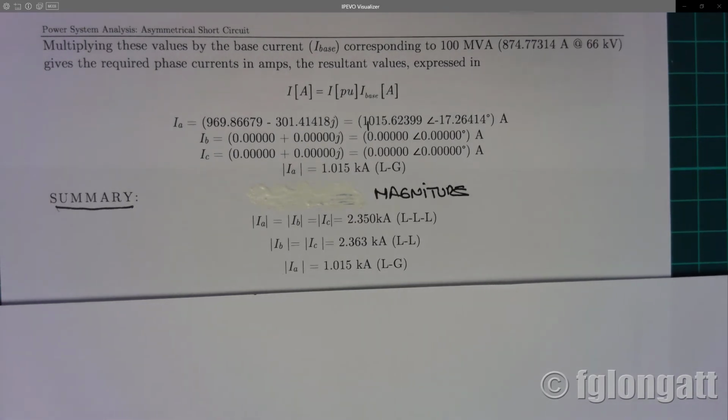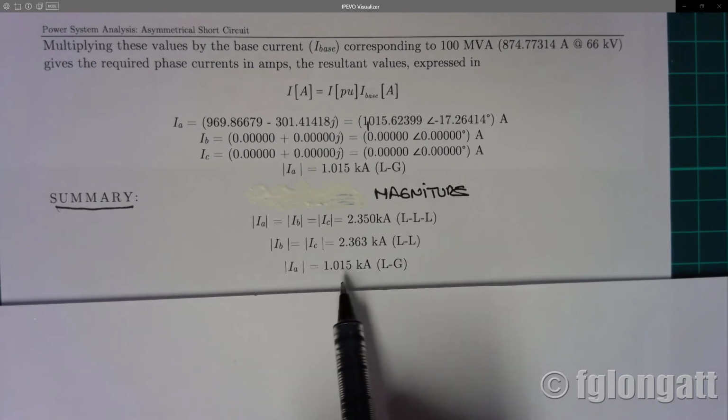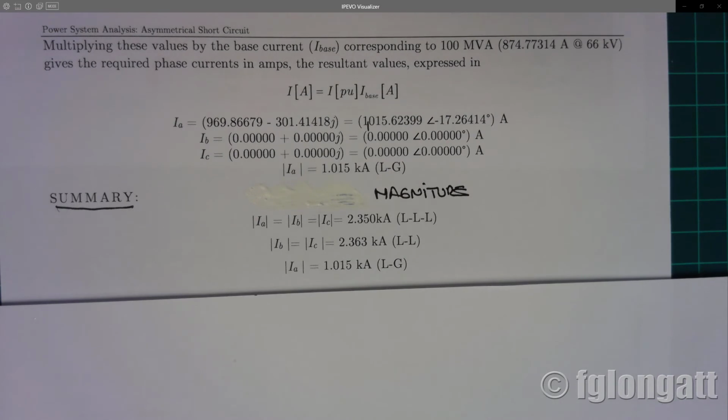At first glance, you might think that the three-phase short circuit is the most serious condition, because it produces the highest short circuit current. However, something I invite you to think about is that the line-to-neutral short circuit is the lowest short circuit current, but it imposes a very asymmetrical condition on the synchronous generator. And to be honest, imposing an asymmetrical condition on a synchronous generator is very dangerous. It's very dangerous because the machine is exposed to an asymmetrical operation that creates stresses, not only electrical stresses but also mechanical stresses inside the machine.